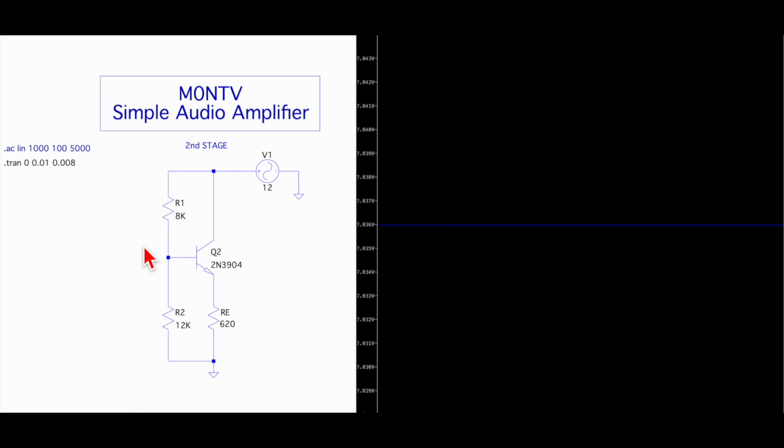And then the top, exactly the same as we calculated the top resistor of the voltage divider in the common emitter amplifier. We say, well, what's the voltage? Well, the voltage is 12 minus what we've got here, which, as we said, is 7. So it's 12 minus 7 divided by 11 times the base current, because remember, we've got that actual base current itself going through there. 10 times there, 11 times here. So 11 times 57.8 microamps, and that comes to 7.8 kilo ohms.